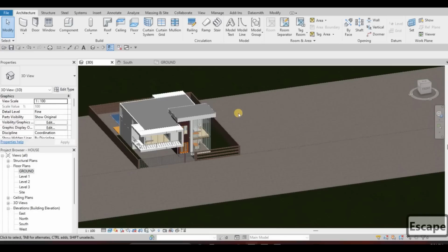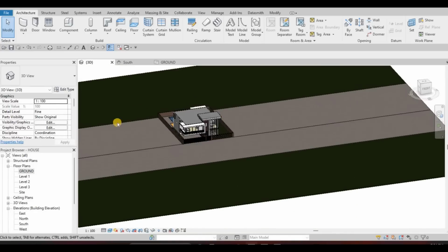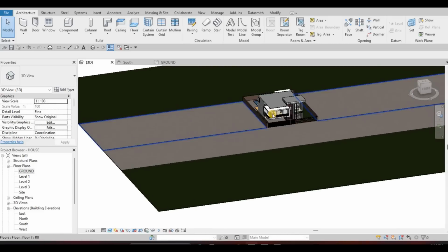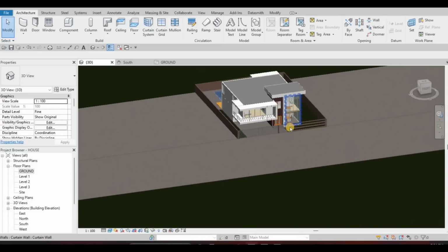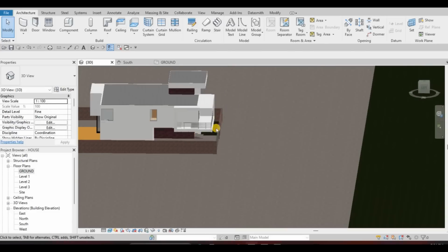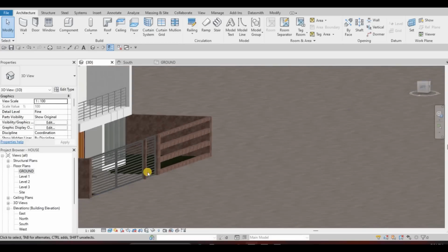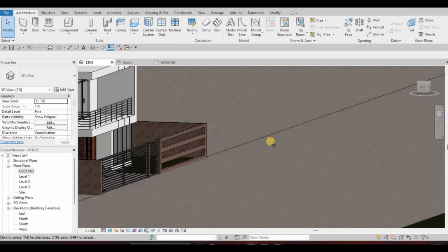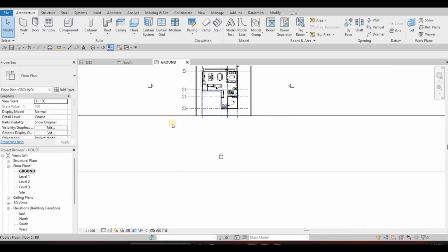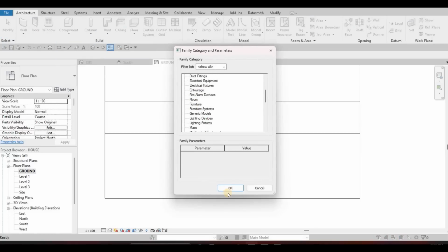And then we could just add in houses here on the side, maybe 2 or 3, and then maybe 2 here, so that it looks populated. And then of course we're going to add the sidewalk. So we're going to add the sidewalk here. So for the sidewalk, we might extend this one as well depending on the look of the sidewalk that we're going to do. I'm going to use model in place for the sidewalk, generic model.